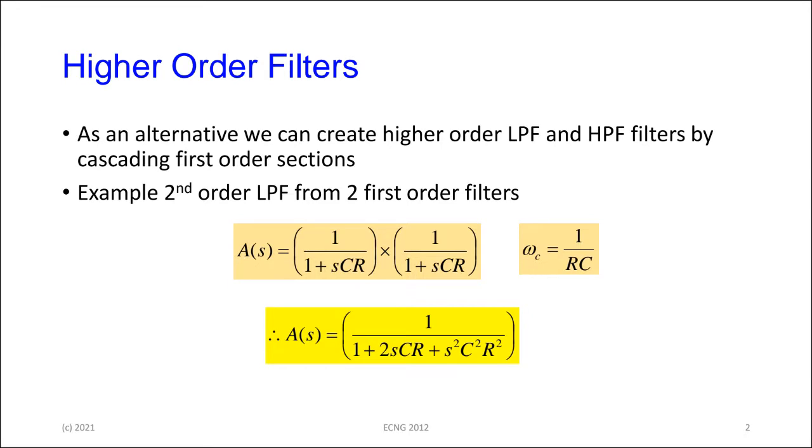So, for instance, the first approach, and we'll also compare the approach to what was done yesterday. Of course, immediately, once you cascade the filters, if you take two first order filters to make a higher order filter, you're now increasing your op-amp count, because you now have two op-amps in the circuit instead of one. As I mentioned yesterday, everything is always a trade-off.